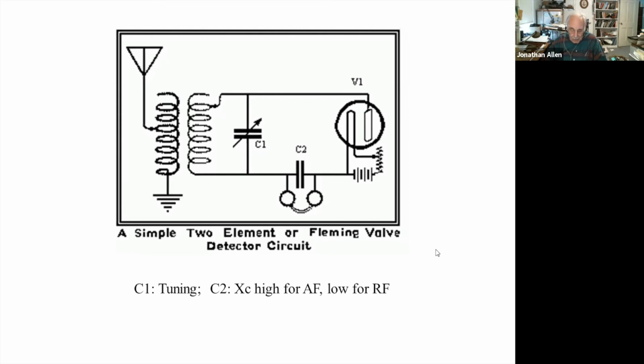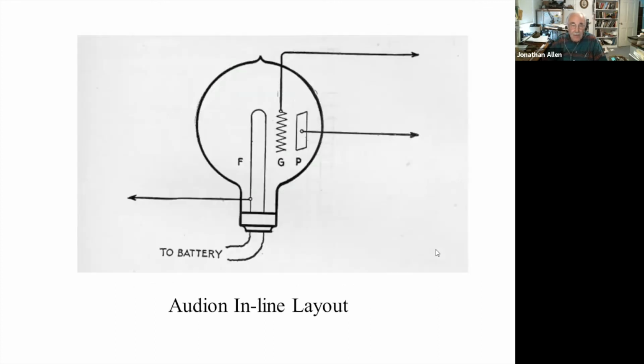So in 1906, he patented a vacuum tube that he called the Audion. And here you can see how it works. Here we have a battery powering the filament. Here you have your hot filament. You make one electrical connection to one side of the filament. Here's your grid, and then you have your plate to collect the electrons. This is just a schematic type of layout.